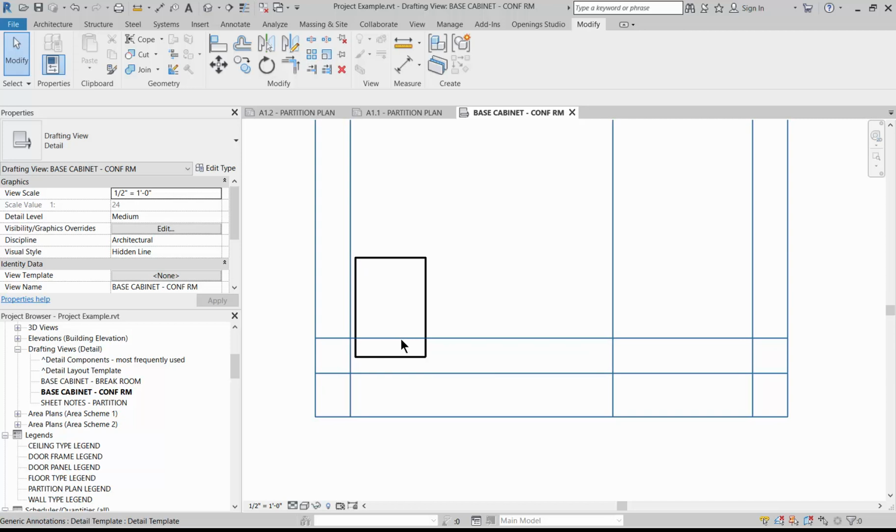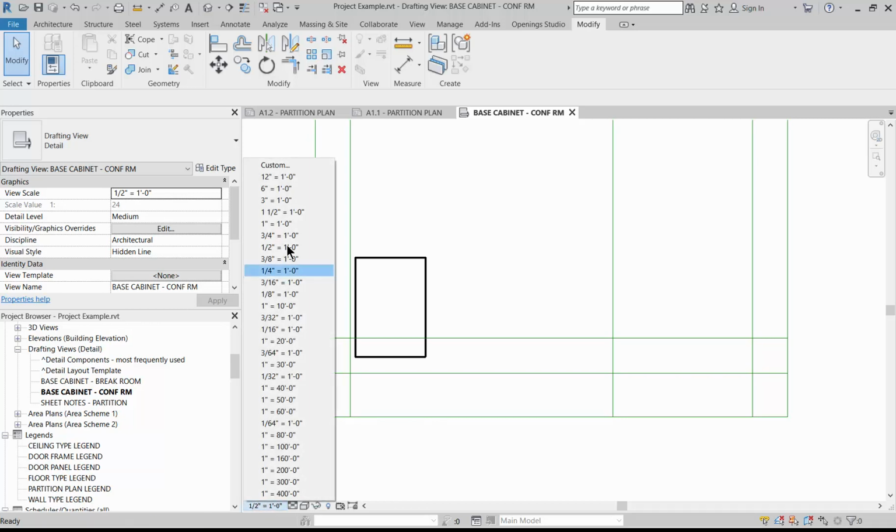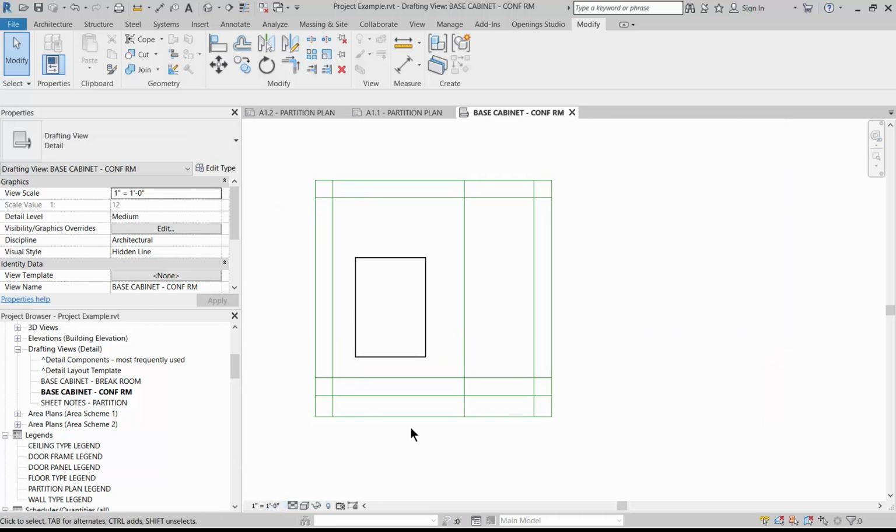1/2 inch scale, not half scale, is essentially just another variation of elevation size scale. It's really a zoomed-in elevation. So I'm dictating the elevations at 1/4 inch. 3/8 of an inch is also popular, and occasionally we'll use 1/2 inch when there's a lot of detail to the particular elevation. So for this cabinet, we are set up with 1 inch to 1 foot, and next we're going to look at the different tools to actually draw this detail.